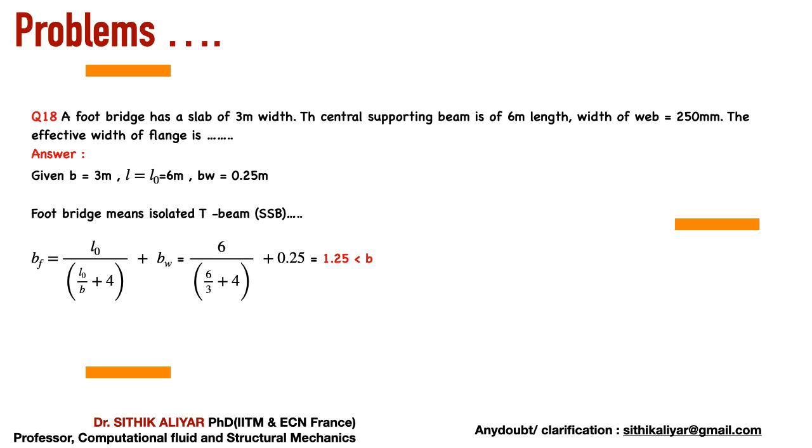So 0.5 meter on the right side and 0.5 meter on the left side of the slab is acting along with the beam. Okay, so I hope with this example you can imagine, so far we have never discussed something like this, because some portion of the slab, 0.5 meter on the right side and 0.5 meter on the left side, is acting along with the beam. That will take some extra moment also, right? So this is a remarkable discovery actually.